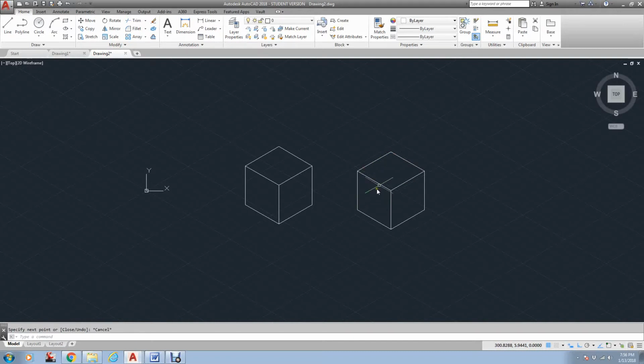If I wanted to show the back of it, I could go line, go to the end of this. I want it to go down. You notice it won't draw me a line down, so I hit F5. It'll draw it down. I'm going to go down 50, and I want to go over 50. And then here I can just go from line from endpoint to endpoint. It will let me do line from end point to end point, and there I've done my cube.